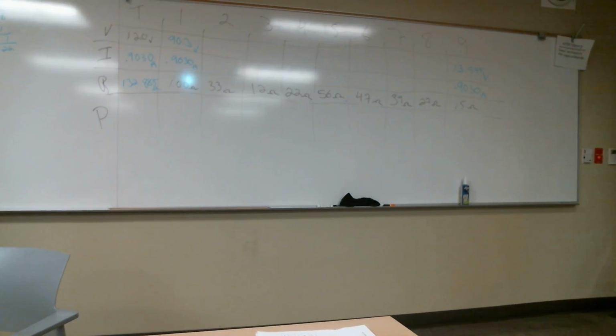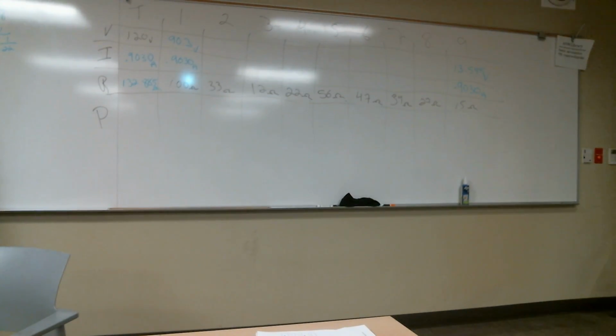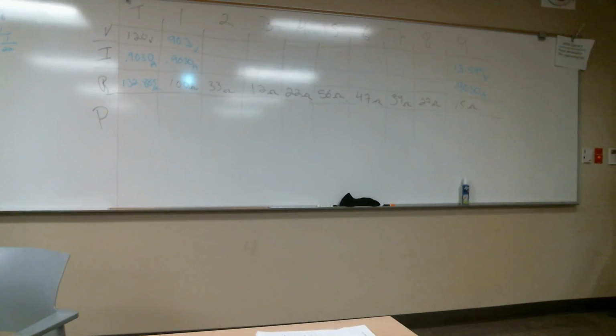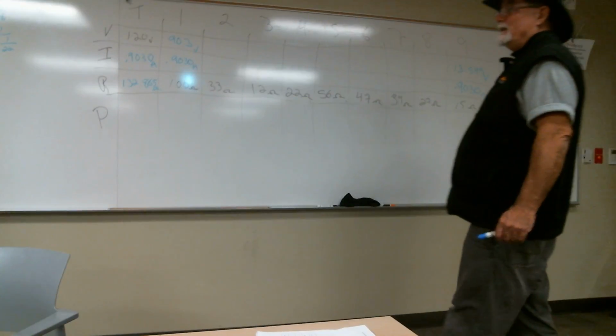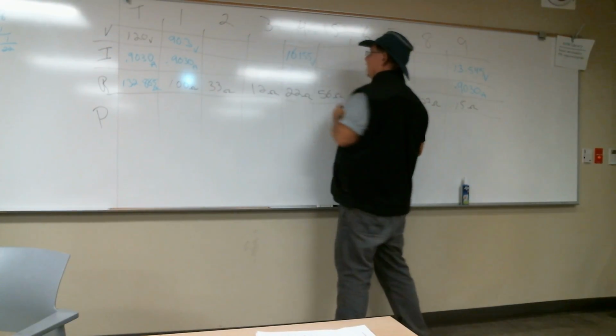Okay, I know what the voltage drop here is, or in this case, it's the voltage rise. So that's going to be 13.545, and that's going to be 29.7. The voltage drop across R4 is going to be the difference between these two, right? You guys are looking at me like, okay, this isn't any different than all the other ones I gave you. So the difference is 16.155, and that's going to be felt across number 4. 16.155 volts being felt across number 4.